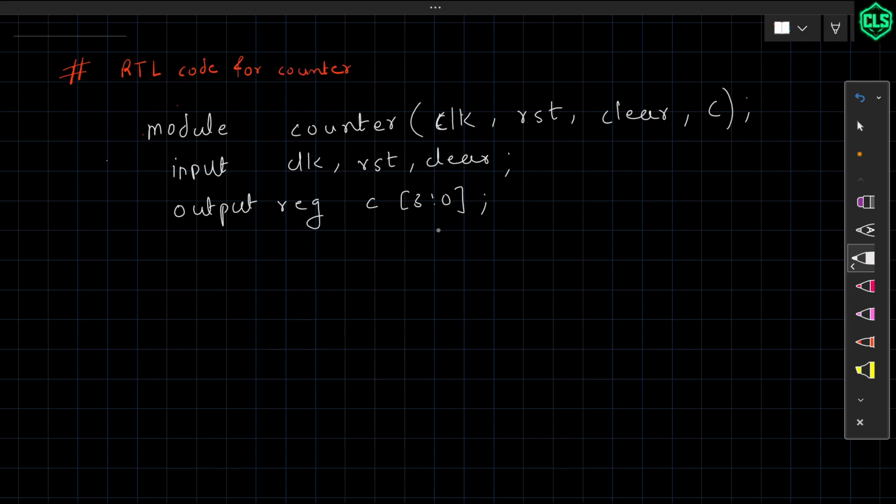But now here one thing: if you use an unpacked array, it will not have a single memory. It will have multiple, like 0 stored here, 1 stored there. But we want continuous memory because it is a counter, right? So we will not write unpacked, we will write a packed array, because counting will be continuous. So we are using an always block, always at the rate.